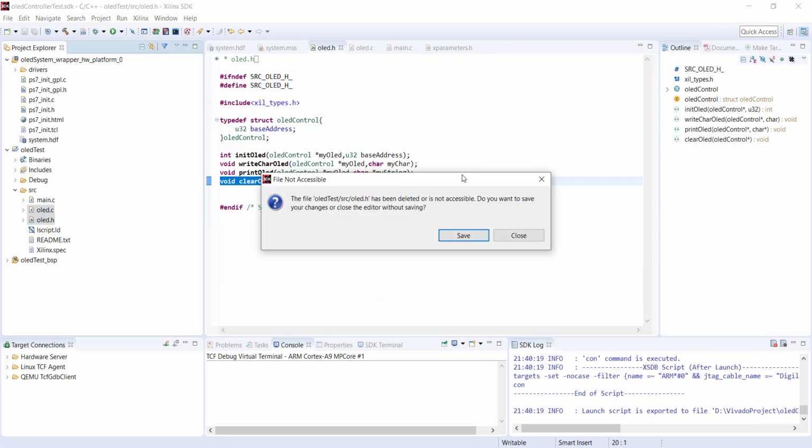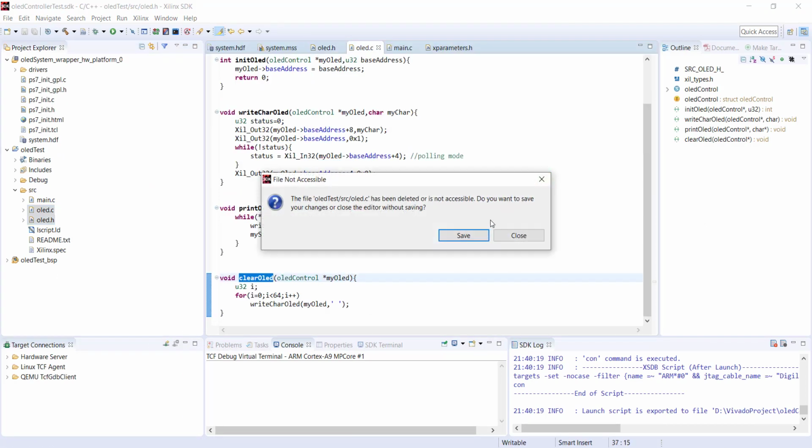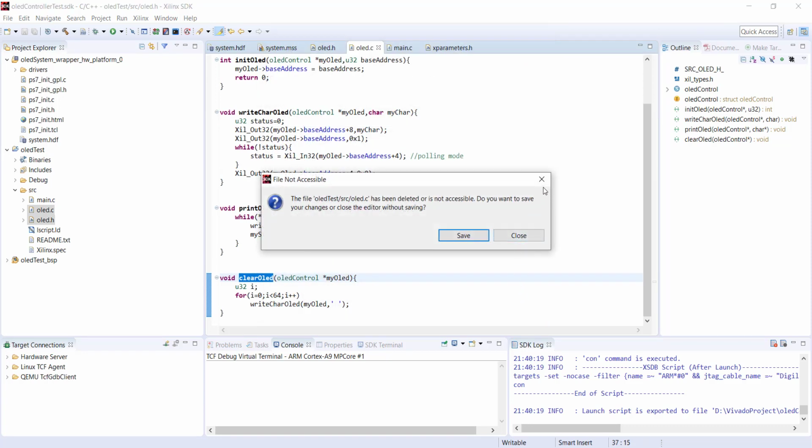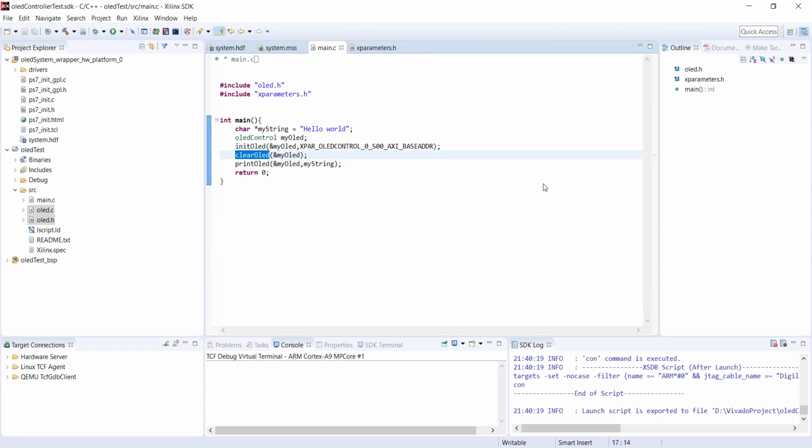And maybe another thing that you can do is, in your hardware, you can remove the entire OLED controller and keep only the SPI controller there, and connect registers directly to the SPI controller. In that case, all the initialization commands have to be sent from the software.